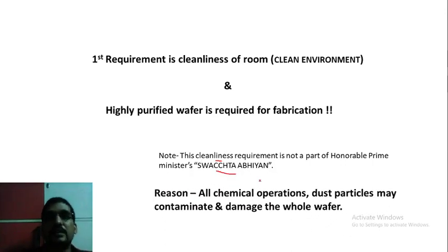The reason behind this cleanliness requirement is that all chemical operations take place onto the entire wafer at once, which we have just seen. All chemical operations take place on the complete wafer at once, and a small amount of dust particles may contaminate and damage the whole wafer, and hence all the ICs manufactured will be wasted. So that's why the cleanliness of the room is required.